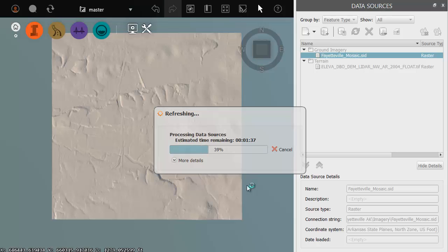We can also bring in SketchUp content. If there are signature buildings in your area, you can take and extract those from the Trimble warehouse. We can drop those models or any of that 3D content into InfraWorks. We can bring in SDF, that's an Autodesk GIS format. We can bring in DGN files. We can bring in DWG as well. We can bring content directly from applications like Civil 3D or 3ds Max or Revit.